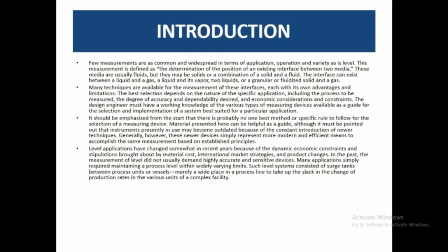If the tank has a temperature of 90 degrees centigrade and you are running that fluid from raw material to your process area, certainly if your flow meter deviates and does not give you the reading of the flow rate, and the temperature transmitter installed in the line starts to rise and comes nearer to 90 degrees centigrade, which is the storage material temperature, that means you need to identify that your flow meter is now deviating and not giving you the correct reading.